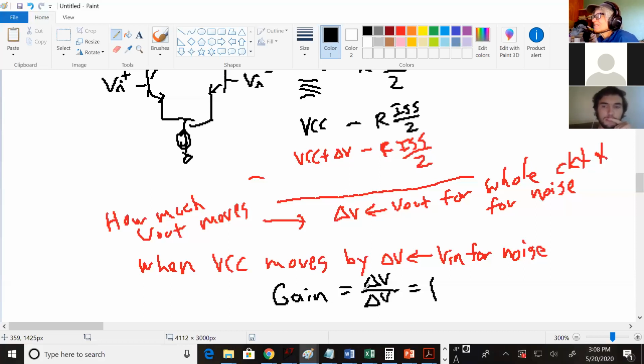It's not bad, but it's not great. Whatever noise you have on the supply shows up exactly on your output. It's not as bad as the common emitter, which is the worst circuit there is for noise on the supplies. So it's just better, but still not perfect. All right. Thanks, Professor. That makes a lot more sense.